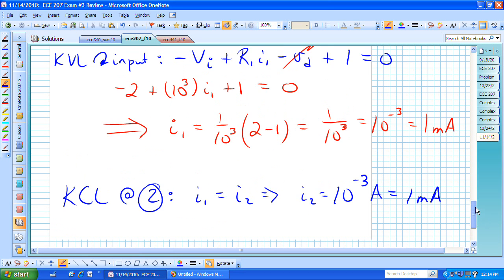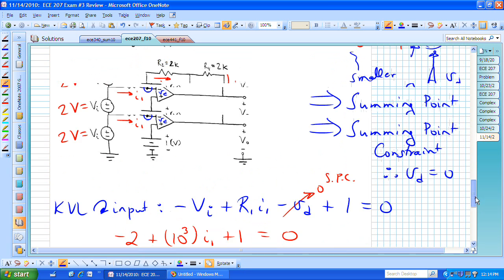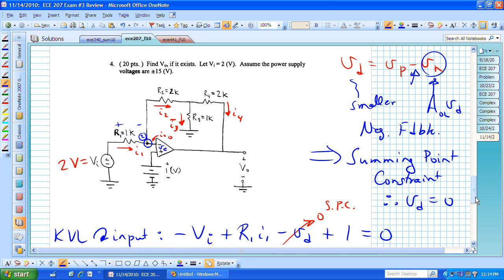Let's now look at, we want to find I sub 3, and we don't know I sub 4, so if we started to write a KCL at that particular node, we would have 2 unknowns. If we actually start working our way through this circuit from left to right, we can do it if we write this sort of sequence of KVLs, KCLs, KVL, KCL in the right order. We can only have one unknown in the equations that we're actually ending up with.